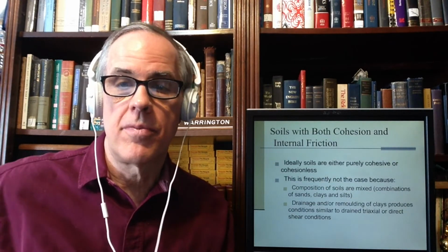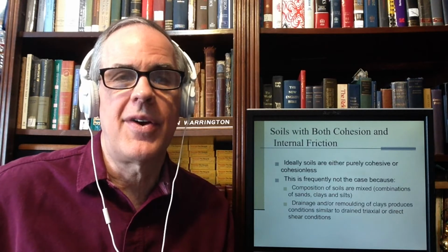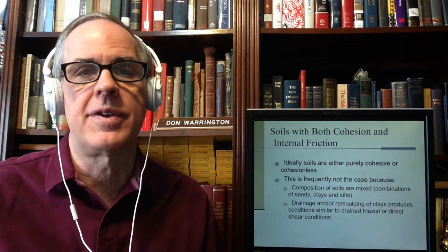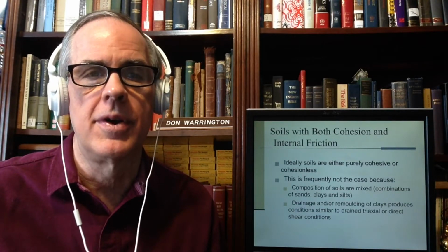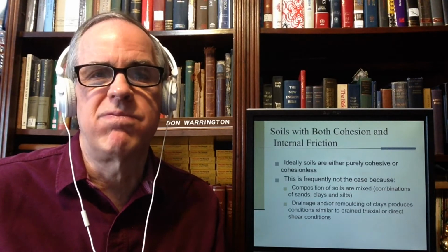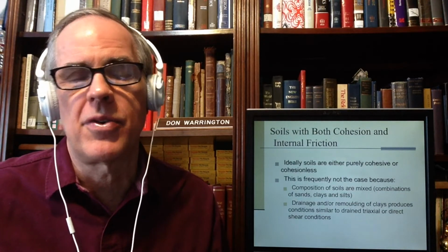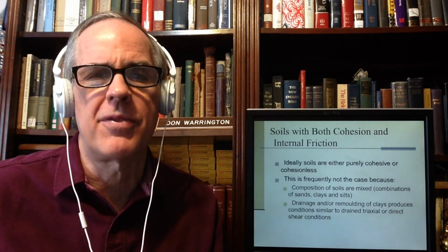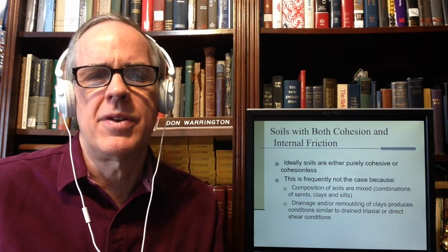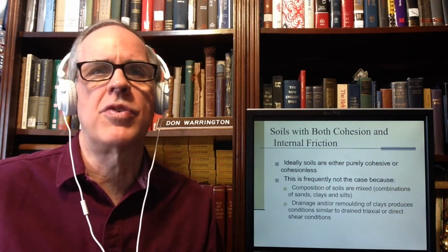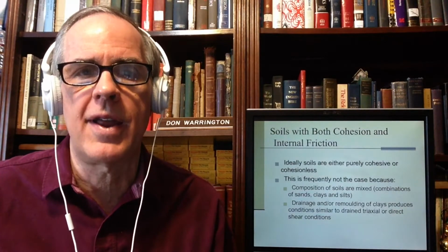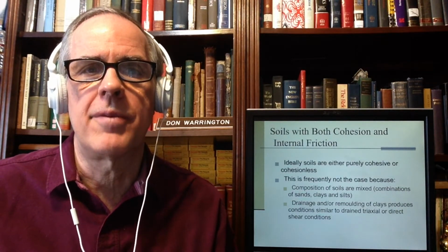Soils with both, traditionally, ideally they're one or the other. There are certain fields of geotech, like deep foundations, that are bad about this, where we just kind of say they're either cohesive or cohesionless, and a lot of our methods are based on that, and that's really not true. But we treat them that way, and because deep foundations are traditionally driven into previously undisturbed strata, we can get away with that.